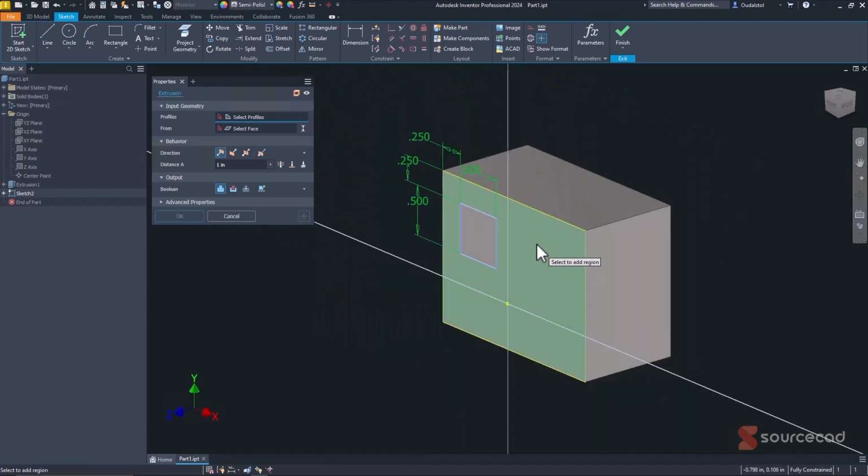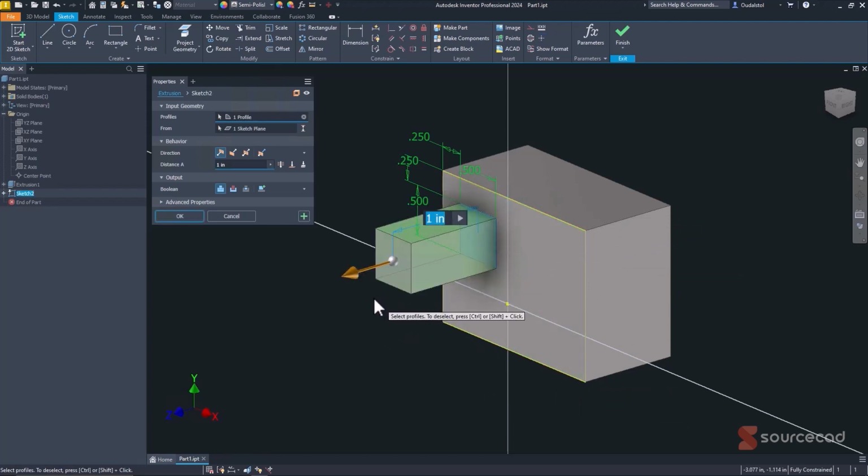Or it's this one. This is because they both have solid boundaries, solid lines that make a boundary, if you will. And so I actually only wanted this one, but I needed to project up these edges to get the dimensions. So I can, of course, just click here, and naturally it wants to go out of the surface to create a new solid portion.